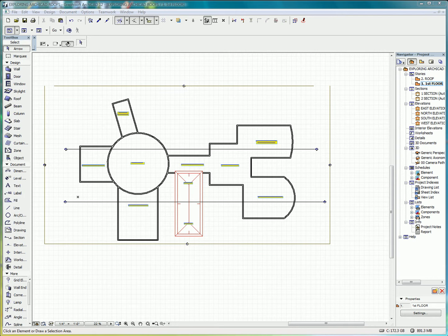The poly roof generates hips, and editing those hips. Roofs are sloping solids of a uniform thickness. Each roof plane can be edited as a single element. Using Control-click to join roof edges. Using Control-click to set spot heights.